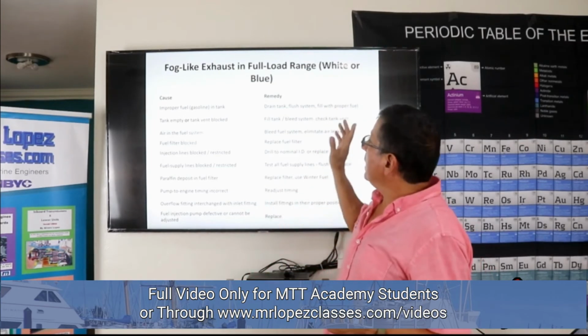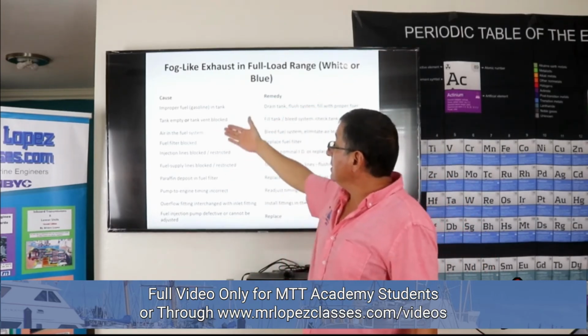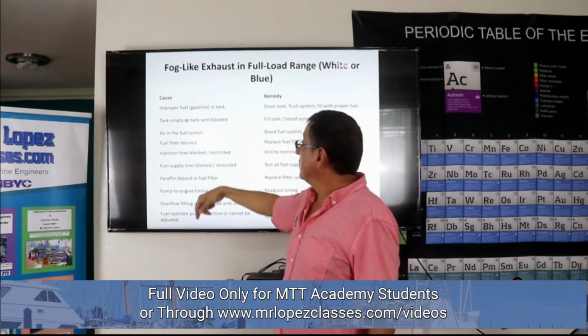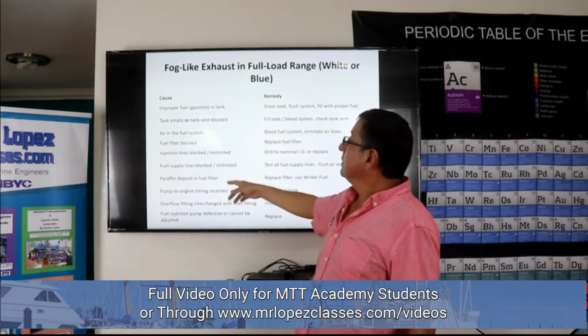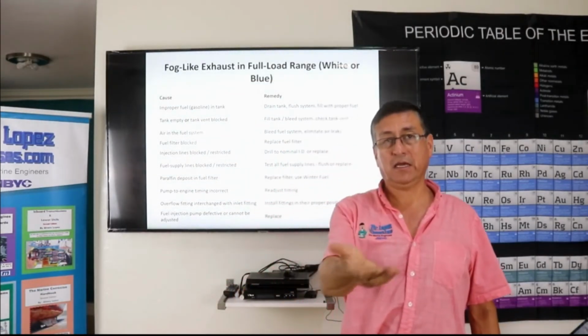All right. Okay, possibilities for white or blue smoke. The tank is empty, air in the system, fuel filter blocked, injection lines blocked. Exactly the same possibilities plus the additional possibilities that I gave to you right now.